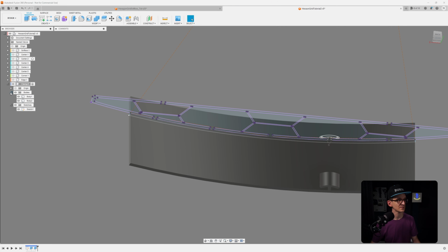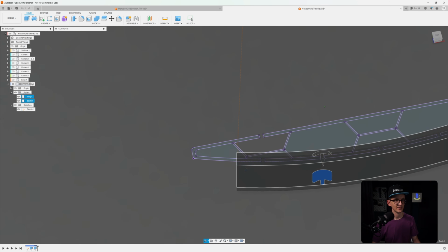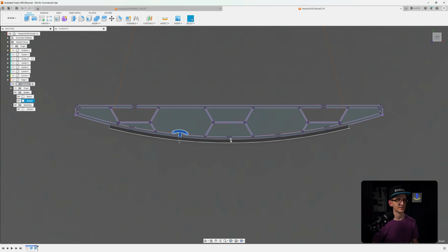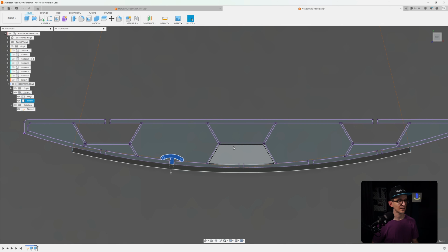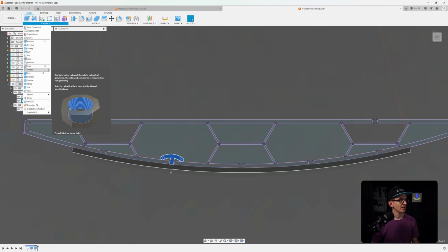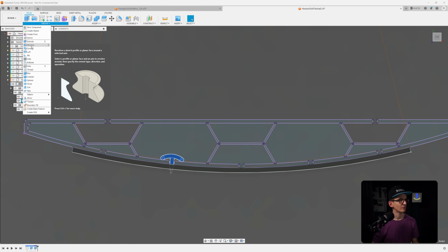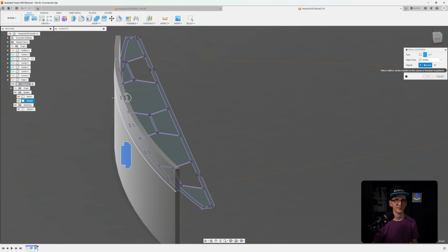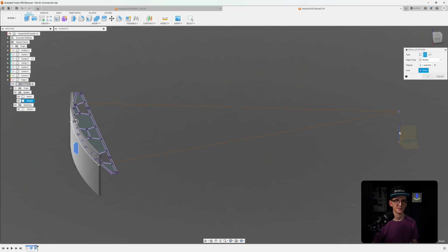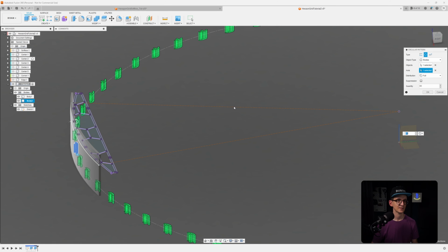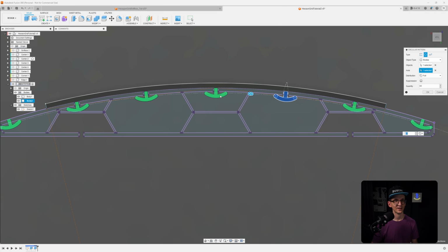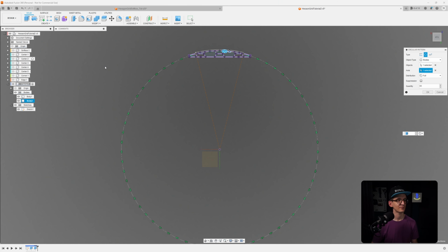Now we have two bodies. We have this piece and the clamps. And now we need to make sure we are able to replicate those in a circular manner all the way where the other openings are. How do we do that? So I would say we can go, for example, with rotate. Actually not. No, we go with the circular pattern. We select the body, which is already selected, and the axis is again the Z axis. We don't need 63. Oh, actually, that's exactly what we want, funny enough, right? Because we know that we have 63, we had those 63 before.